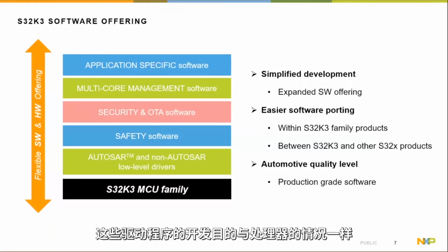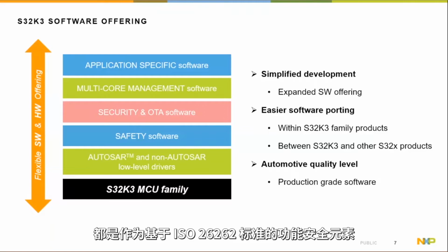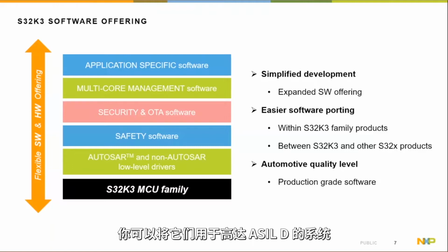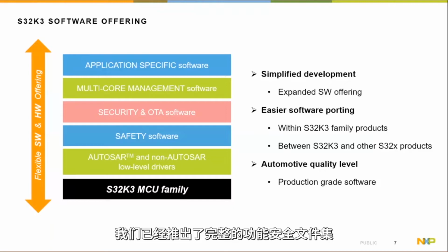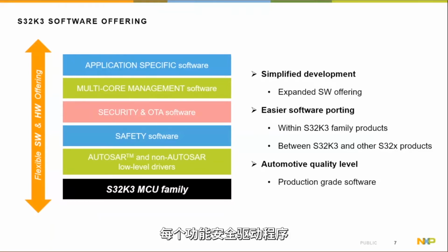The drivers are developed like the processor as a safety element out of context in accordance with the ISO 26262 standard. So you can use them in applications up to ASIL level D. And we have the full safety documentation set available like we do for the processor. There is an FMEDA document or FMEA available for each safety driver within RTD as well. In addition to that,